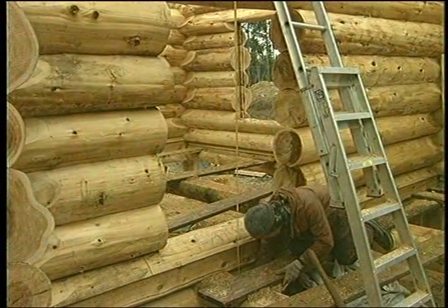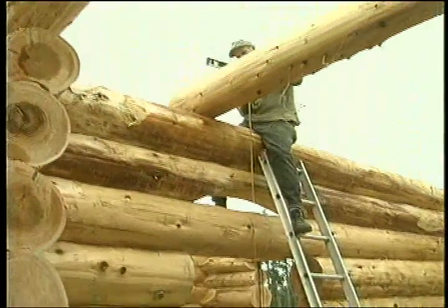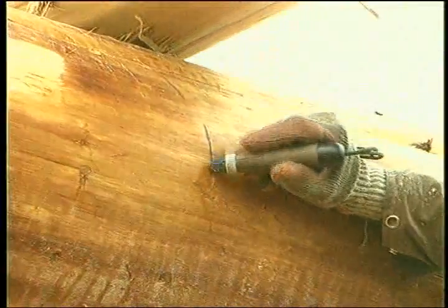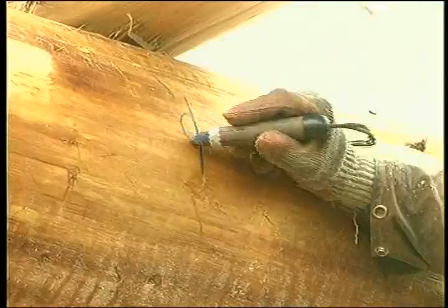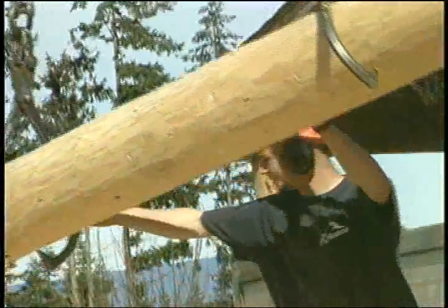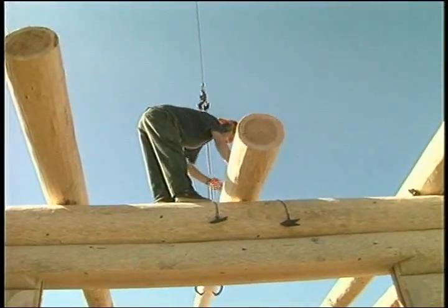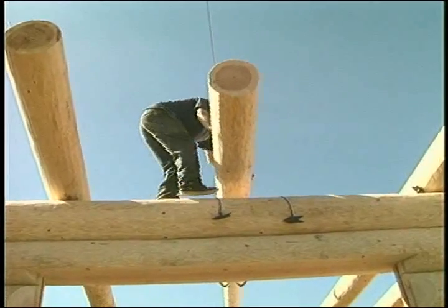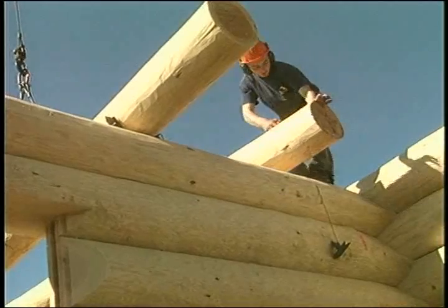You can measure right from the foundation if that is more convenient. Now mark off the centers for the joist locations, then place the selected joist material up on these positions. If there is to be a balcony or extension to one end, you may want to place the large end of the log in that direction.